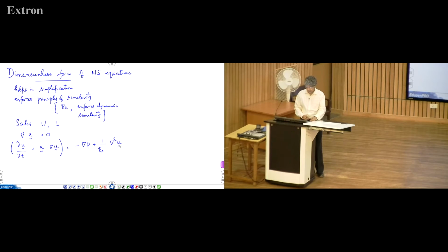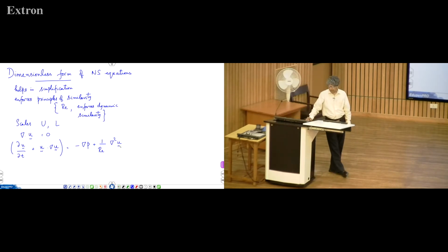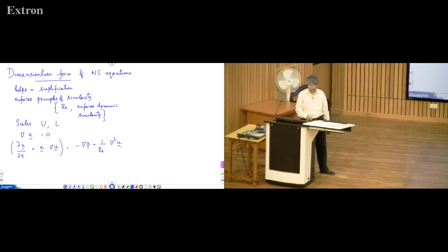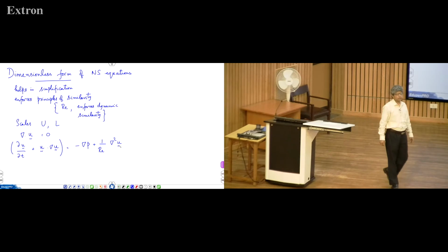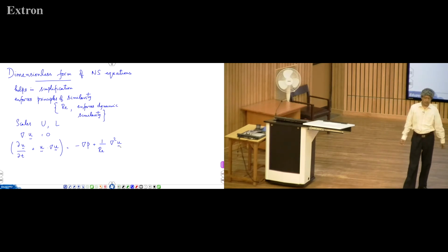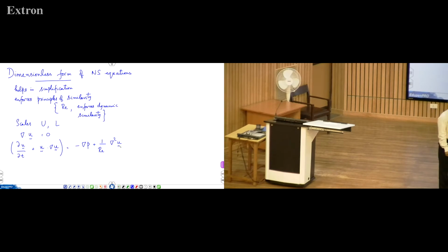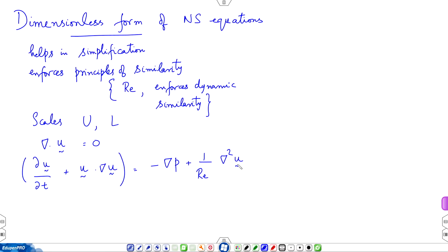So, this is the non-dimensional form using the vector representation of the gradient operator del. You can't solve this system, for that you have to go into the specific coordinate system, Cartesian or cylindrical. So, del has to be represented in that coordinate system, then you write out the equations. Now, in each coordinate system you have a slightly different method for obtaining the solution.